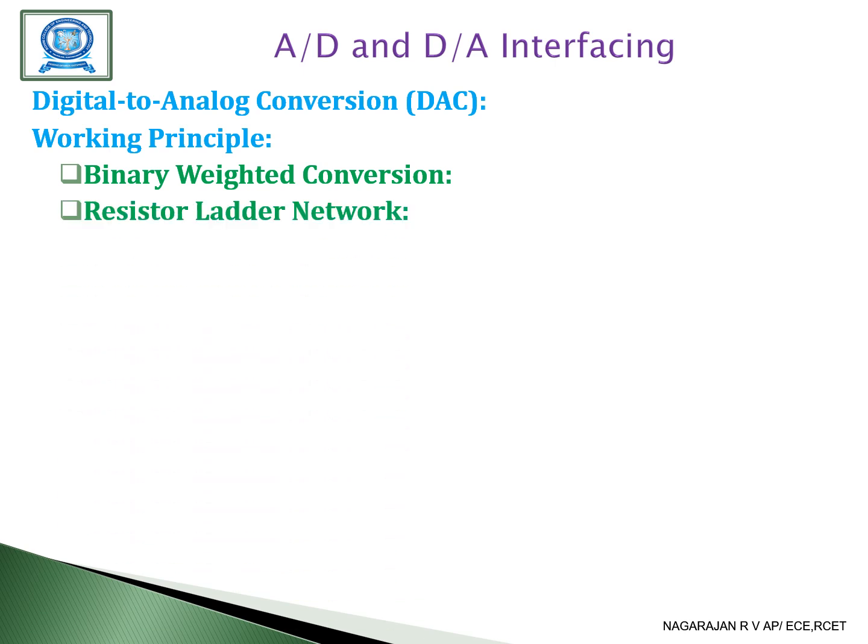Next, resistor ladder network. A common technique used in DAC where resistors are arranged in a ladder configuration to generate the required analog voltage from the digital input. The next one is output smoothing. The output of a DAC often requires smoothing to eliminate steps and produce a continuous analog signal.